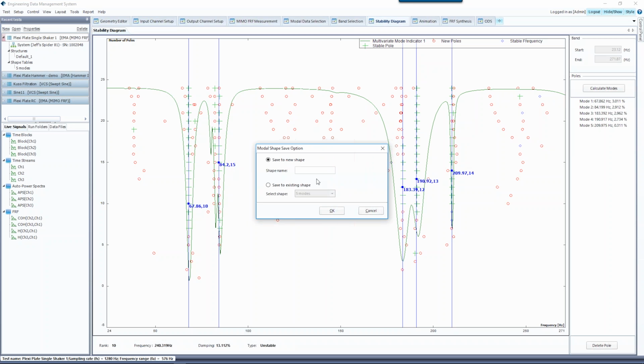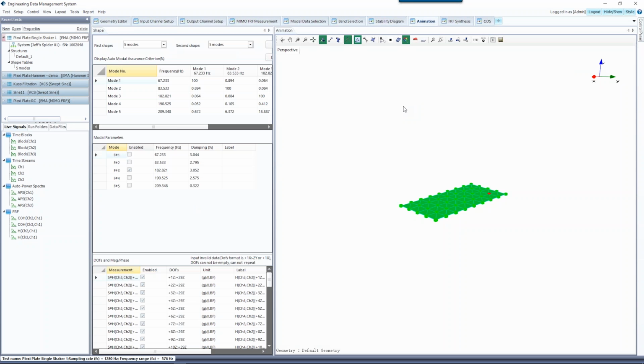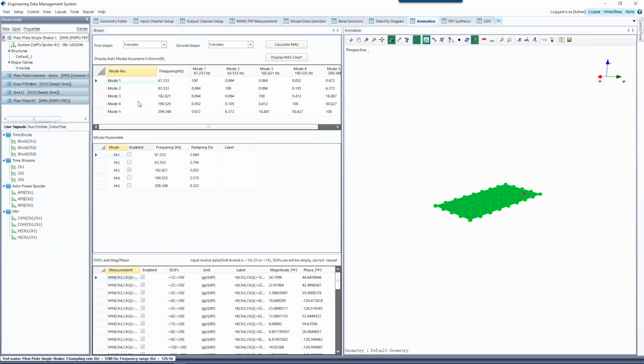Typically, modal analysis is carried out in two steps. The first step is to identify the poles, using the LSCE method to find the natural frequency and the damping coefficient. Once this is done, it is used to calculate the mode shapes. The mode shapes are calculated from the residue values from the FRF equation.